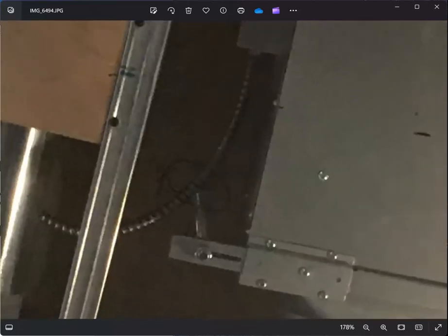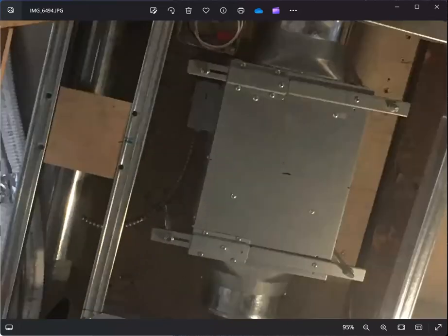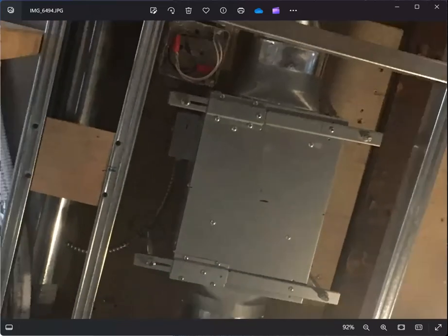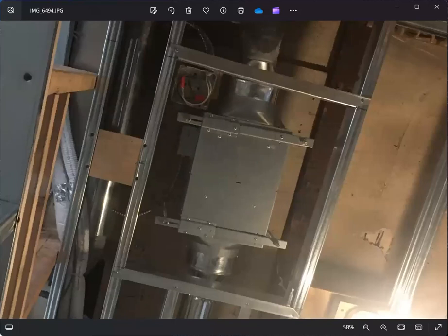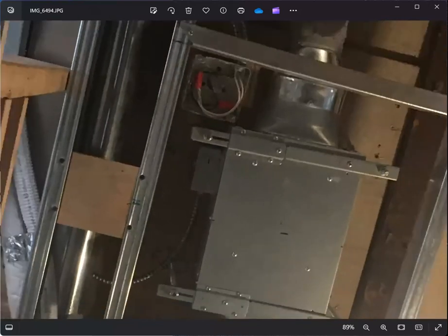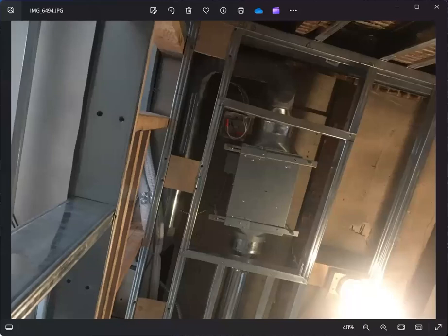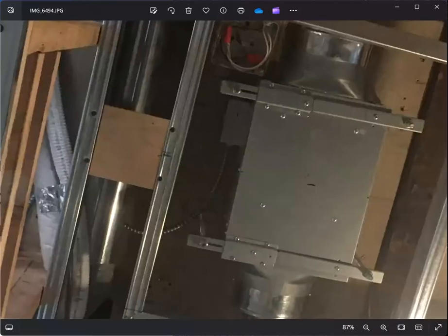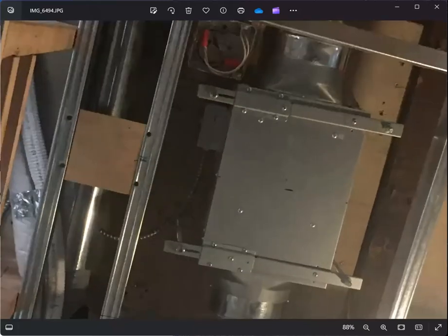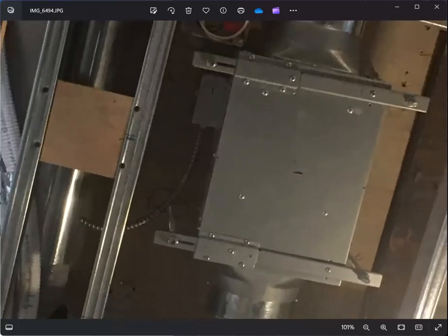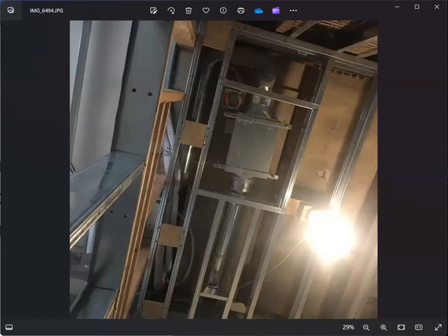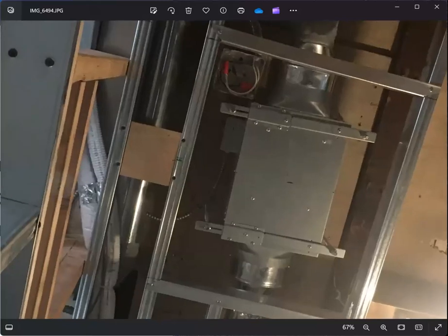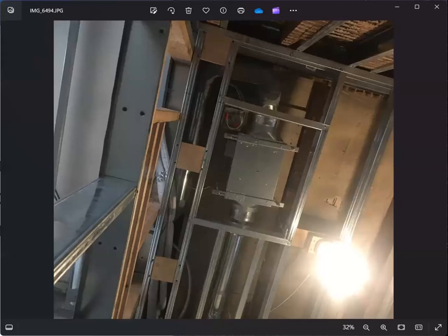Sometimes for a small unit like this, they need to put an isolation rubber so that if it makes some vibration, it has absorption. That's to prevent the breakage of your ceiling. If it runs for a long time, it might break the connection of the support from the ceiling, if there are no vibration isolation devices.